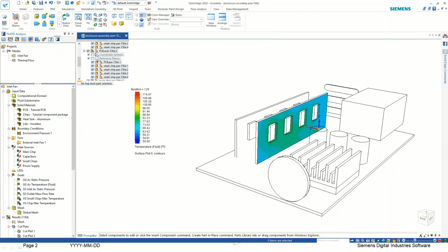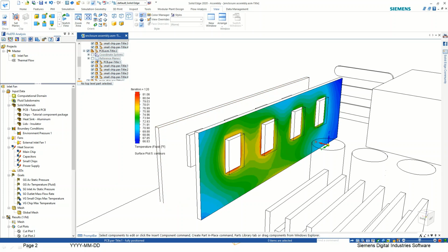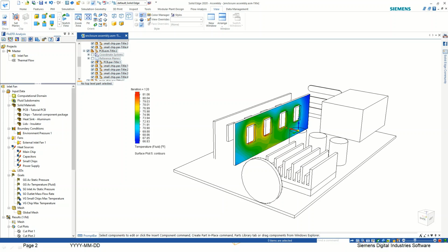So along the surface you will have a range of fluid temperature, and you'll see that it varies from 66 to 81 on this particular face. Why I'm saying it, because the second option limits me to the maximum and minimum of this face only, and not to the global. If you want to see the global values and the color according to that, you can go to the first one, which is reset to global maxima and minima. When you apply it, it will give you the response as per the global temperature distribution, but this is a better representation to get a clear idea. So this is one way.